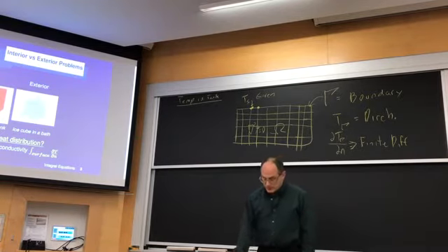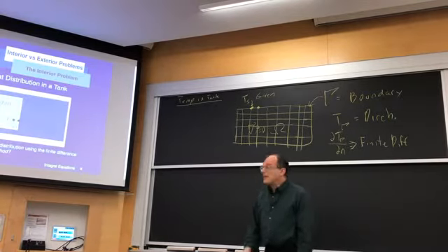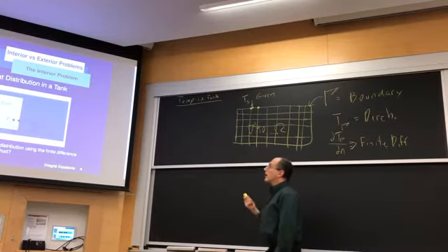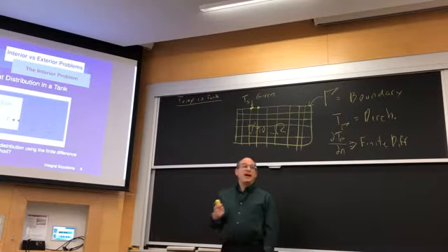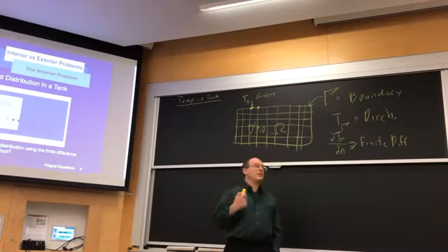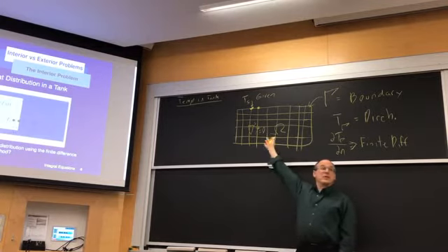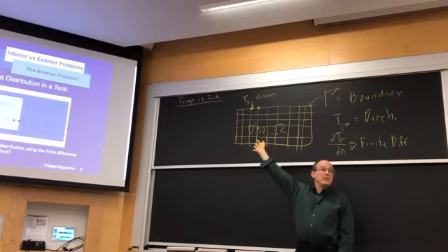For integral equations, we would do it a somewhat different way, and I'm going to try to show you that in a moment. So, we do heat distribution in the tank, we set up the finite difference grid, we solve for the temperatures everywhere inside, and if we only want the heat flow into the tank, how many of those temperatures do we actually need when we do a finite difference method? If we're interested in heat flow, we only need the temperatures near the surface of the tank. How many do we have to solve for? Do we have any nice way of solving for just the surface temperatures? No, we've got to solve for them all.